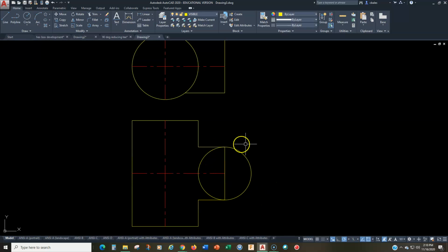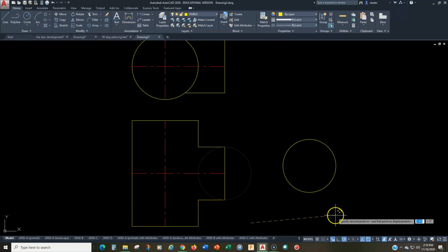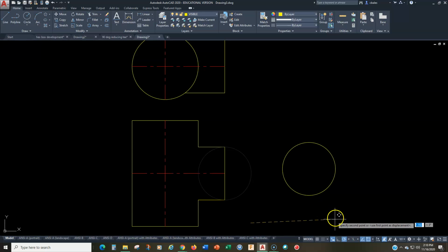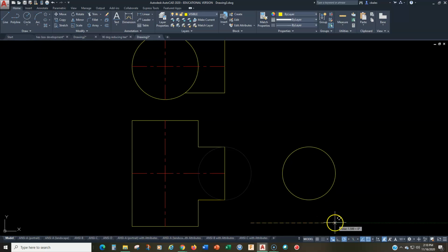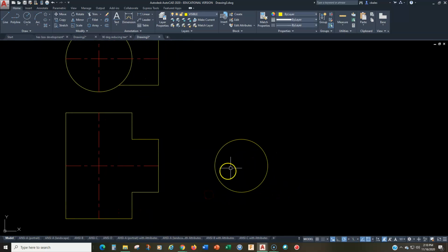All right. So I'm kind of using the geometry that's already there, and then I'll move that over here a bit, making sure, again, I don't want to move it up or down. I'm just moving it directly across, and I'm going to keep it kind of close also for the same reason as before. We can always move it if we need to. All right, so that's the end view of that. And now the rectangular view, the vertical tube.